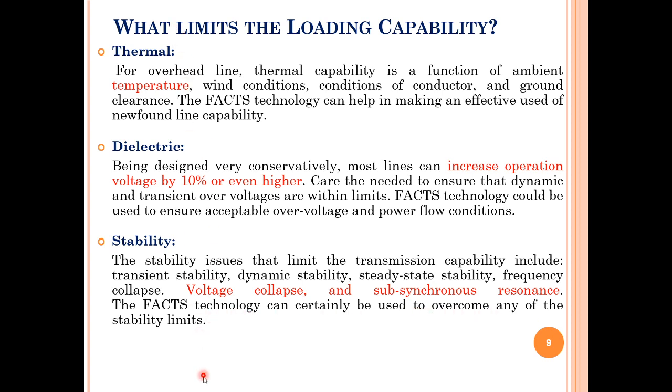These are the three main points for which thing? Loading capability limits. Don't forget, thermal is directly related to temperature. Dielectric increases the voltage by 10% or even higher. Stability also can cause voltage collapse and subsynchronous resonance. Altogether, I'd like to have some alternative. That one is nothing but FACTS technology.